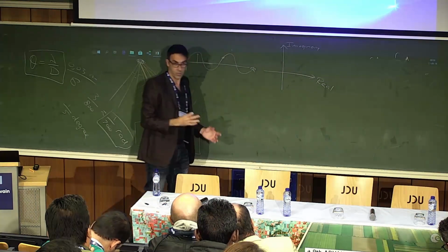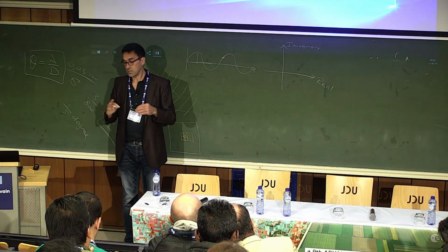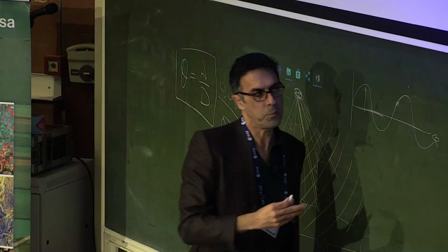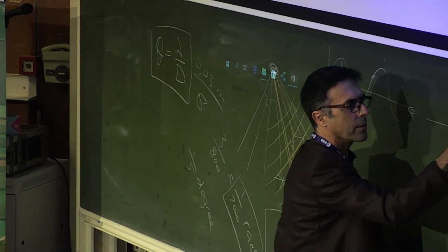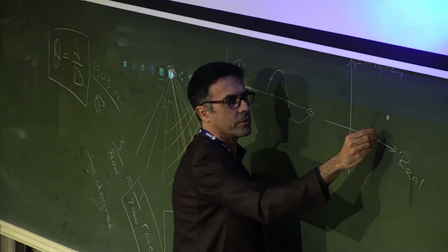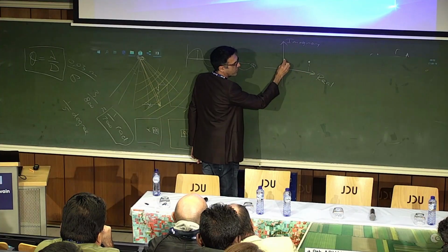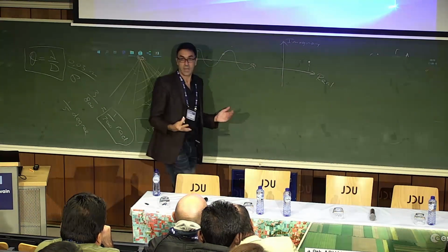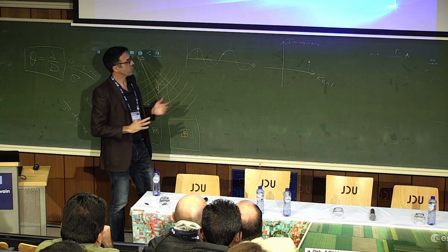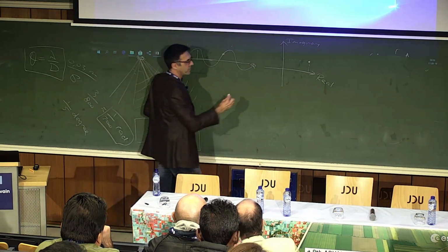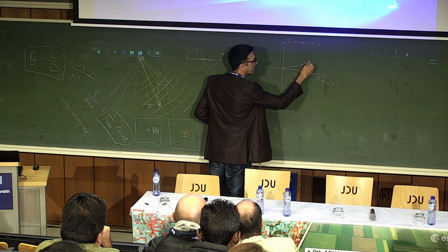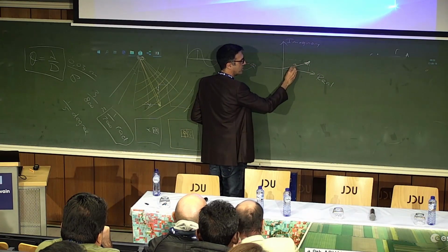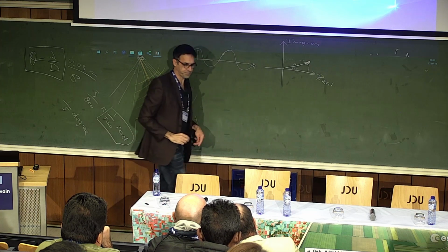And one measurement for 1 pixel in a SAR image is a dot somewhere in this plane. So let's say maybe here. Now that dot could then be explained with a real valued number and an imaginary number. If I have these 2 numbers, I know how to deal with it. Or I denote it with an amplitude and a phase. That would be an arrow here. Right? So this arrow has a certain length, call it the amplitude, and it has a certain phase.